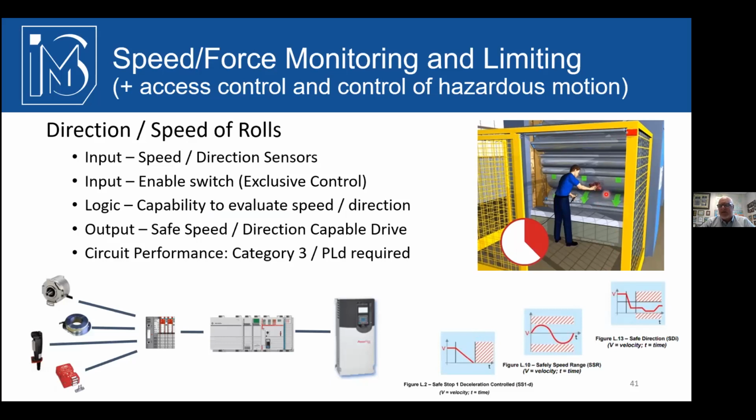Normally, this would be a very hazardous in-running nip, but I need to clean both of these rollers around all 360 degrees of it, but I can only access maybe 20 degrees, 30 degrees of it at the most at any one time. So it'd be really nice if I could keep these rolling in a safe direction, outrunning nip, and also at a slow speed that will allow me time to wipe these down, clean them with some sort of solvent or whatever I'm going to use, get them clean as they move while I'm in there. And you can see in this case too, I've got an enabling device. He's holding on to that in case anything ever happens. He can let go or squeeze it and it would come to a stop.